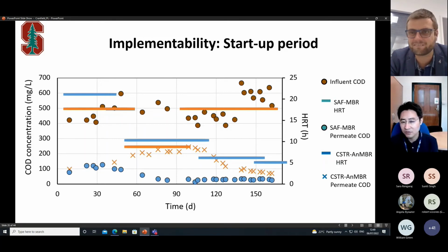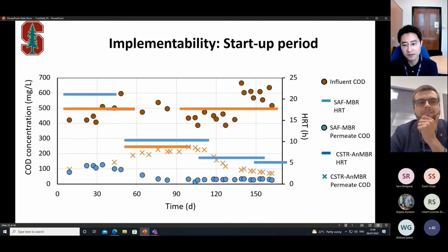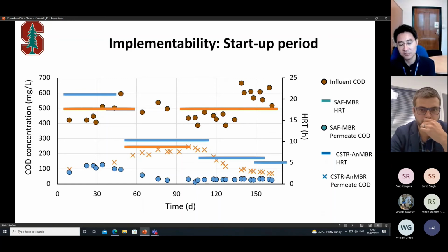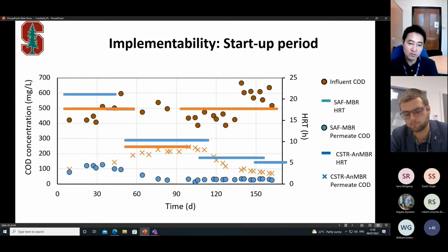Okay, I guess the most challenging part is to create the biofilms, how you can gently mix things and not get clogged. If you have a high concentration, I don't know if there are a lot of solids inside. So the one we have is a microscreen. In the pilot scale, we use 2 millimeter quite small particles. Those particles can get into the system, as in a AnMBR system. So I guess that if you can control most of the solids and also get really good recirculation, that might work better in our understanding.